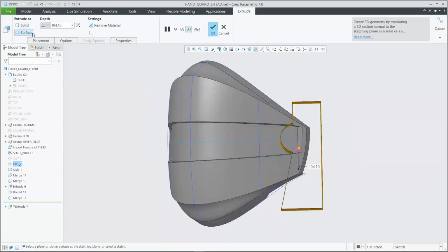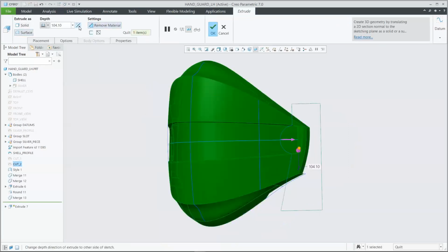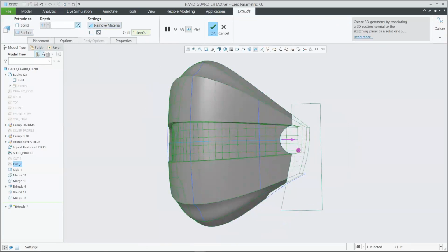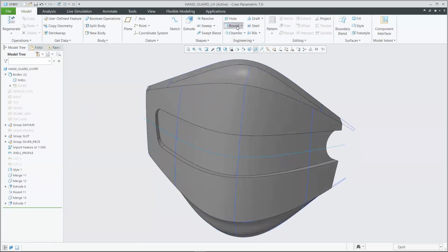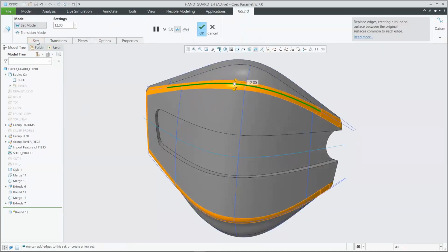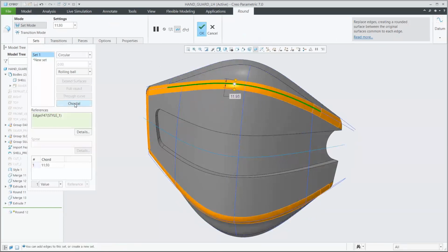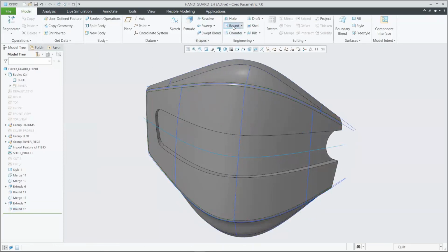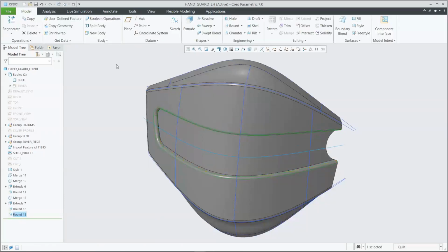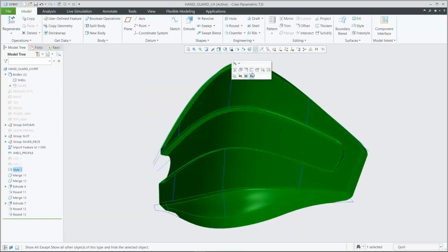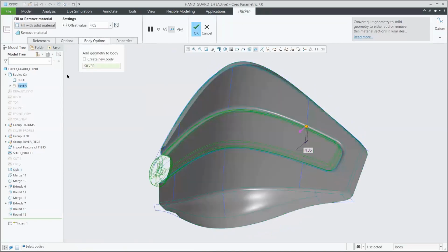There's also another area over here on the side where the cover is going to attach back in with the rest of the assembly. So we can remove the material from that section as well. And then same as before, we can use some smooths or some rounds to smooth out the hard edges that we have in some of these surfaces. Rounding is very robust from within Creo. Maybe we want to do a quarter round around the outside edge of the front surface. And then for this inner edge, we'll just go ahead and keep that at a constant radius. All right, now everything's laid out how we like. We can go ahead and give this a thickness to that quilt, which in turn is going to turn this into a solid model. And there we go.